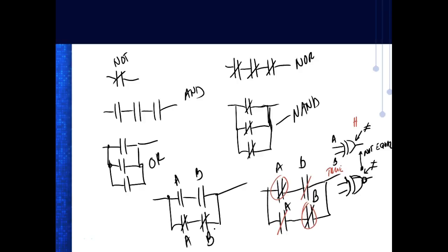Of course, back in the intro to PLCs, this is where you learn the Boolean algebra. So if you can mathematically express a circuit, you can do it in a Karnaugh map. The problem with Karnaugh maps, and I hate them things with passion, is that if you get over 4 inputs, you're going to have 16 entries in your table. If you go to 5 inputs or 5 control devices, you end up with 32. You go one more, you end up with 64. And you get a table that's so dang big, it's hard to figure out what goes with what, all the rooms and the corners and sides and stuff like that.